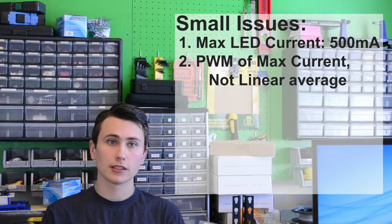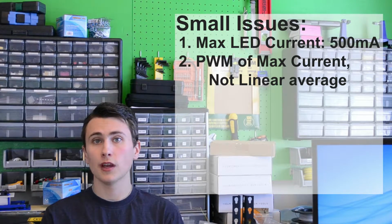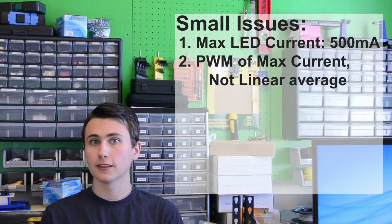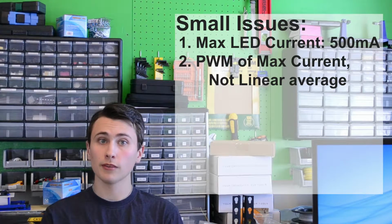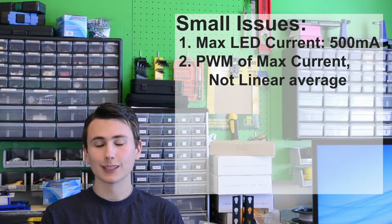In the second iteration of the design, the maximum current was set in hardware to 333 milliamps by changing the current sense resistor from 0.2 ohms to 0.3 ohms. And this lets the RMS current be set to anywhere from 0 to 333 milliamps. Since our set point was 300 to begin with, this current set point is equally valid. This small change fixes the issue.